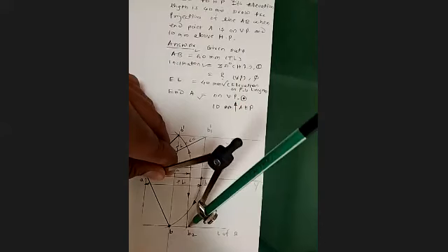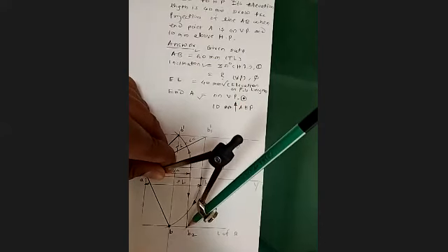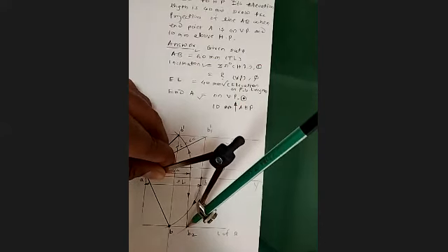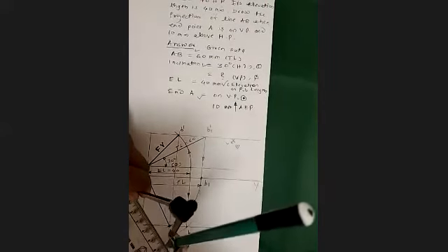You just ensure that you are getting the exact answer or not. A little error is quite obvious and it is acceptable. See, if I keep the compass at A, I am getting the same point exactly, right? I am getting the point. Understood? If I take the measurement in compass, 60 millimeter, without even having taken it at this point, I got it by taking the projections from here, but still it is going to give the exact answer, right?